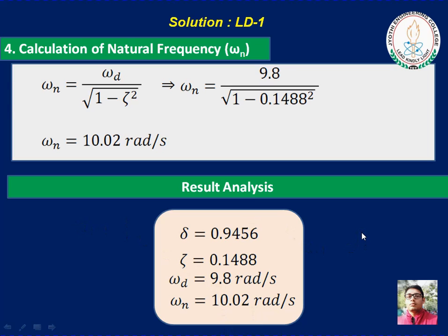So today we discussed the concept of logarithmic decrement, how it can be calculated from successive oscillations, or between amplitudes separated by n oscillations. Using logarithmic decrement, we calculate the damping ratio, and using the damping ratio, we calculate the damped frequency and compare it with the natural frequency. These are the things we discussed so far, and we will meet with another topic. Thank you.